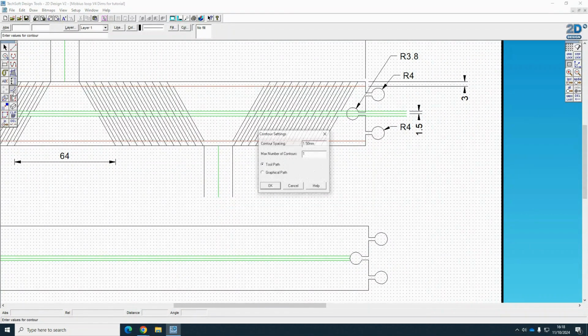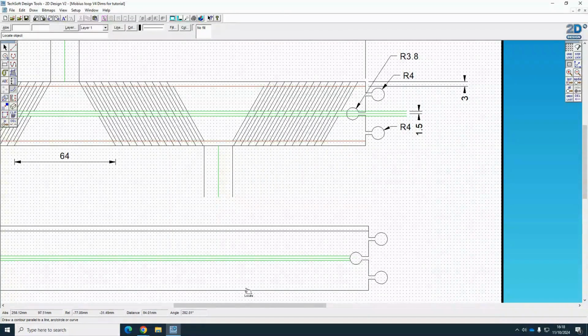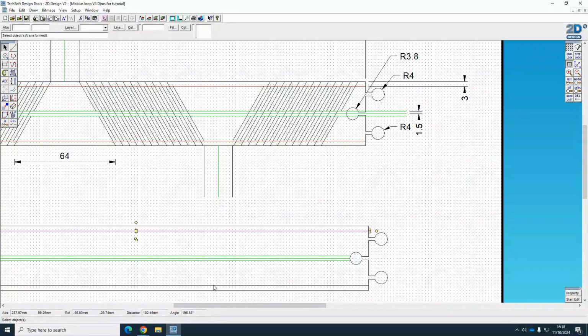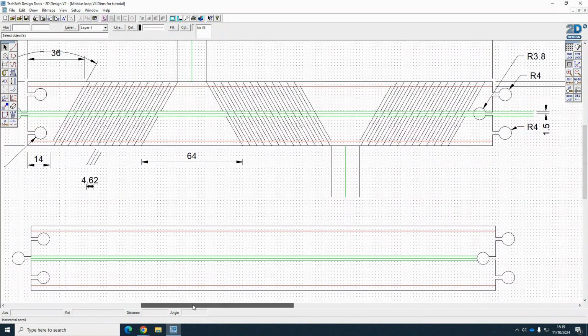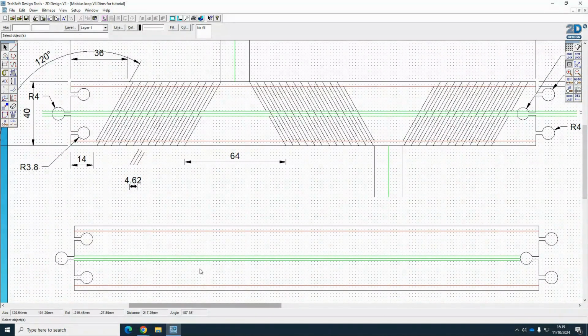So select my contour tool again, change my spacing to 3. There we go. Select that one, press shift, select that one, line color, red. The color isn't really important here, it's just for me to understand that those lines need to be deleted afterwards, they're just guidelines, okay?